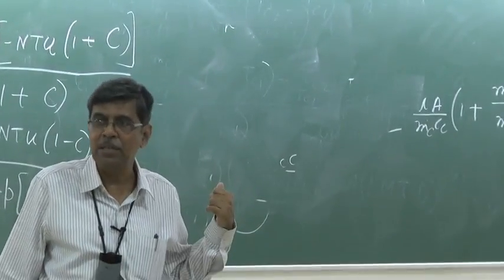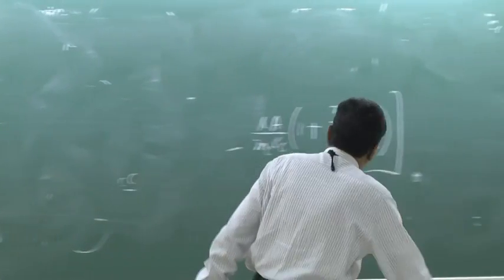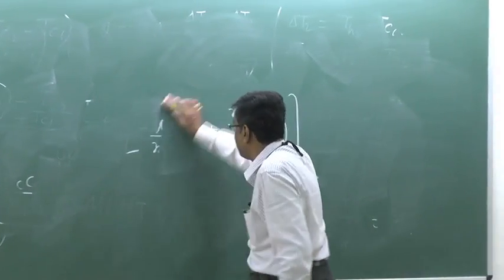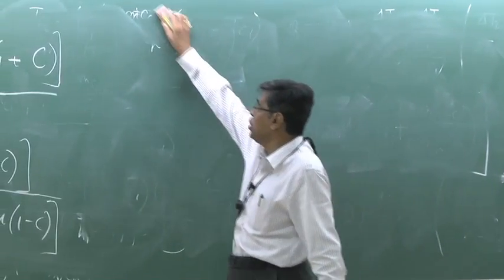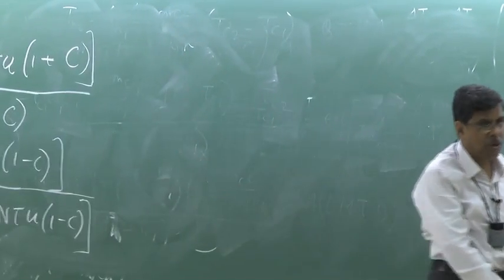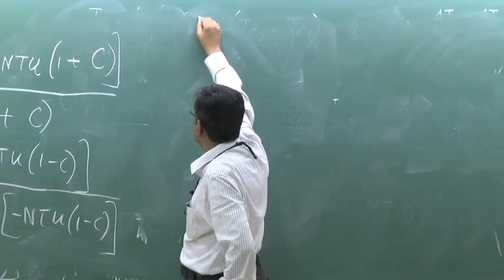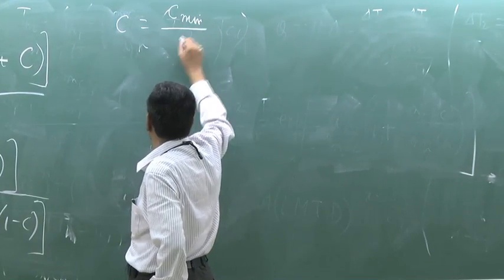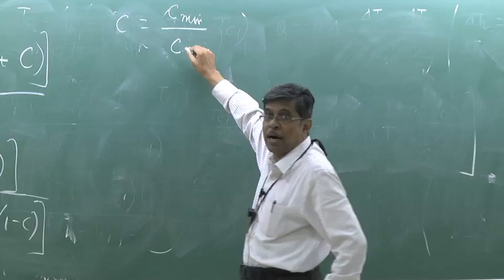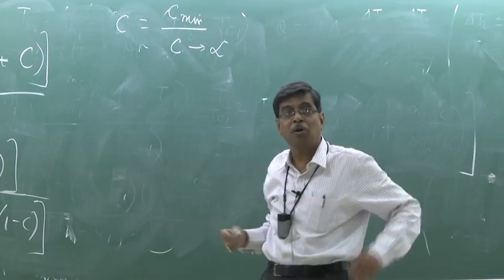But now mathematically you see that for a condensation and boiling problem, the specific heat of one of the fluids tends to infinity. The fluid which is boiling and the fluid which is condensing has C infinity, as I showed you earlier in the figure, so the higher C tends to infinity, because it will always be higher.